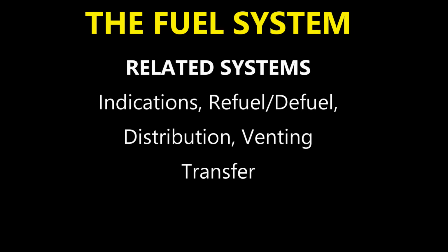Because we want to have a certain temperature. Fuel temperature is important, so we don't want too hot of a fuel running through the recirculation pipes. Okay. And of course, your fuel return valve that's part of the recirculation system is interfaced with the FADEC. The FADEC is the one controlling this valve, regulating it.